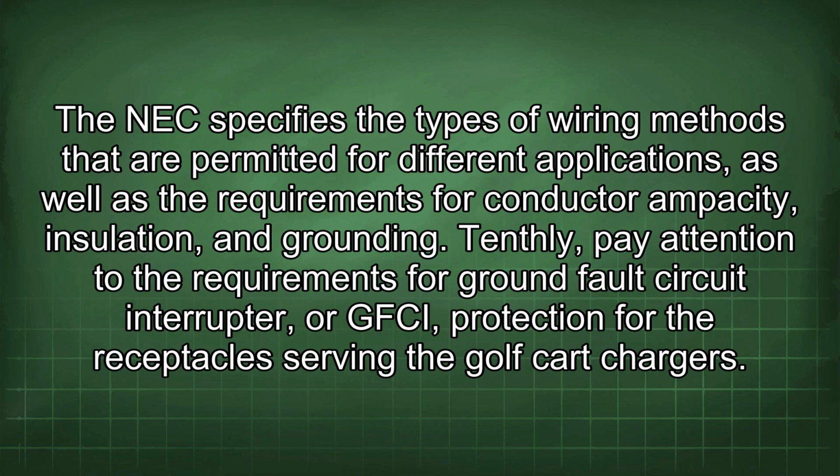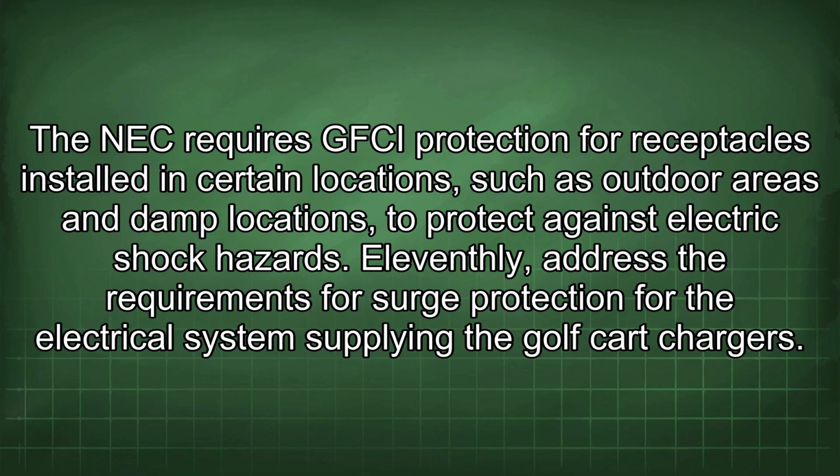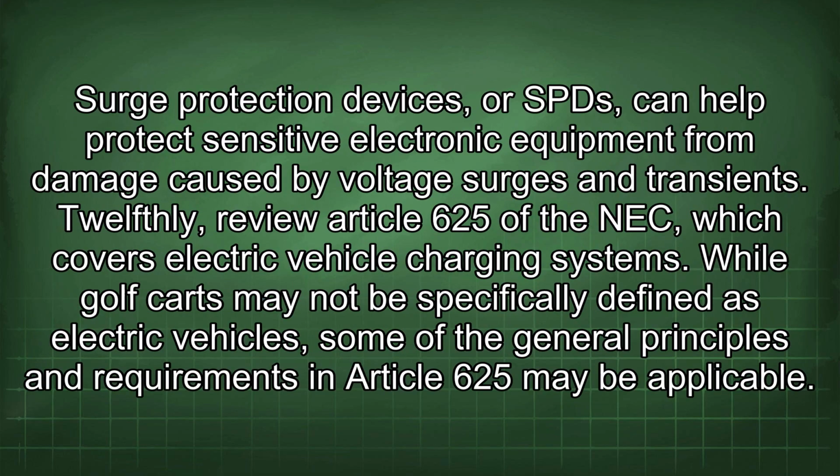Tenthly, pay attention to the requirements for ground fault circuit interrupter, or GFCI, protection for the receptacle serving the golf cart chargers. The NEC requires GFCI protection for receptacles installed in certain locations, such as outdoor areas and damp locations, to protect against electric shock hazards. 11thly, address the requirements for surge protection for the electrical system supplying the golf cart chargers. Surge protection devices, or SPDs, can help protect sensitive electronic equipment from damage caused by voltage surges and transients.